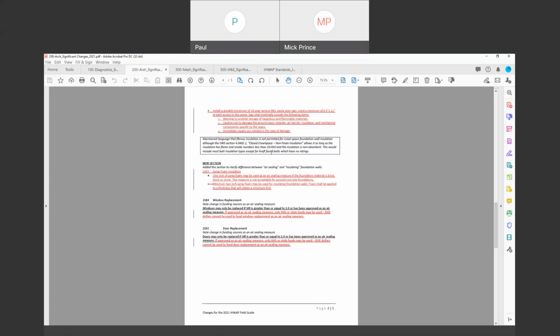Yeah, and if you don't get the air sealing perfect and you've got cold air behind that insulation, it's getting wet back there. I think a lot of people have probably pulled an old batt out of a box sill and the foundation wall is wet behind there. Yep, that does happen. Yeah, seems like a building durability issue.